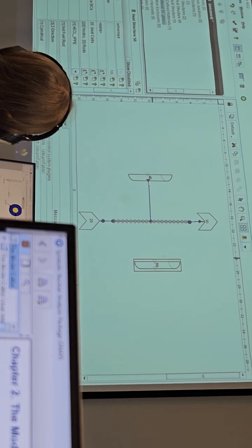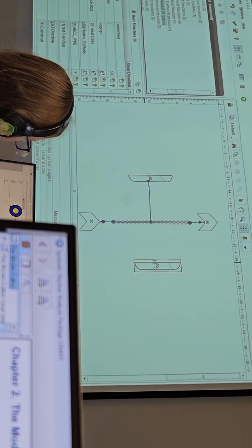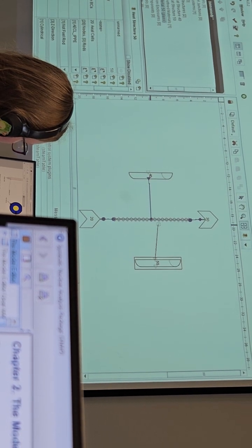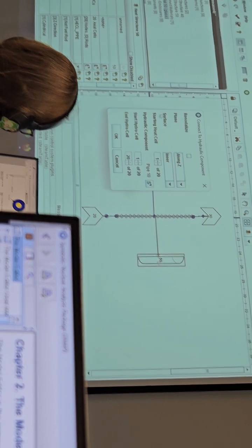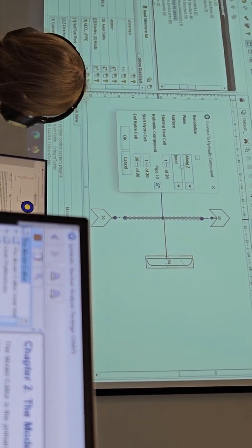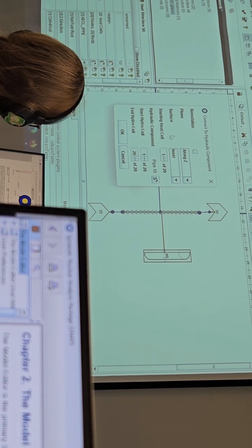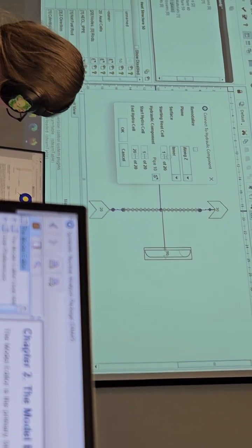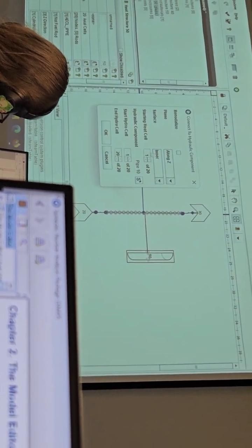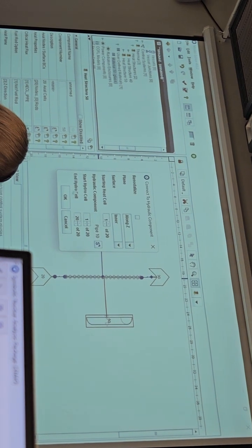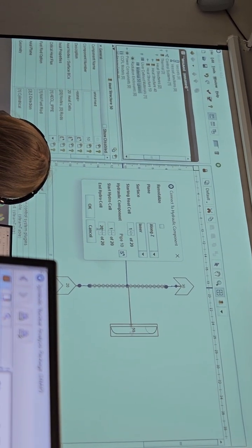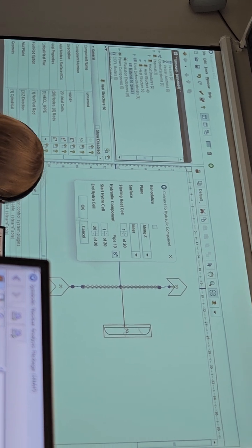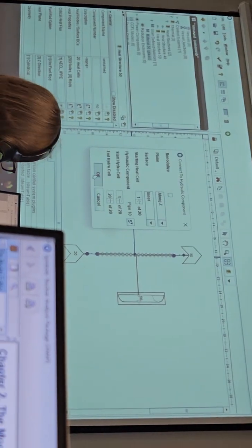Then we need to connect our heat structure to the pipe the same way as for all other components. Here also plane along Z direction, surface inner in this case, starting cell and so on. We can leave it as a default one since it is connected for the whole pipe length, and then just press OK.